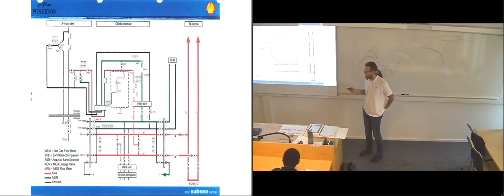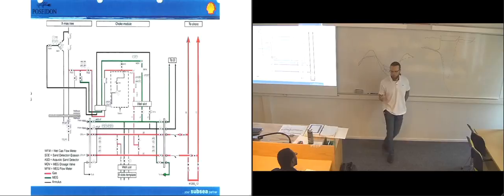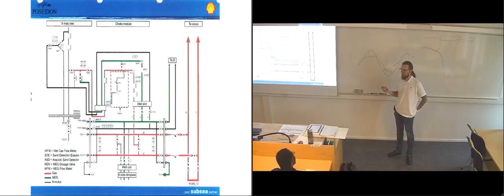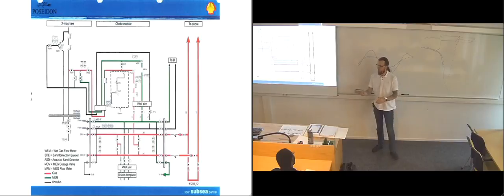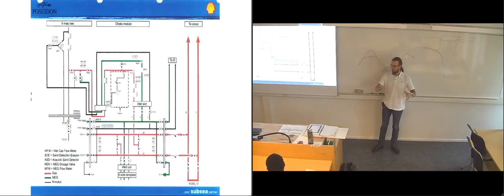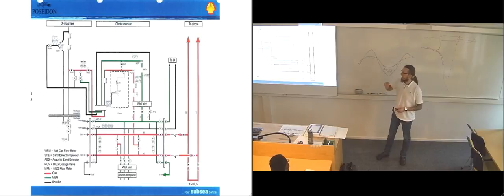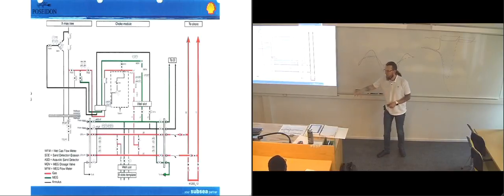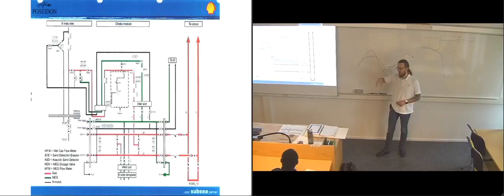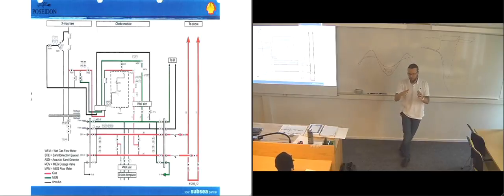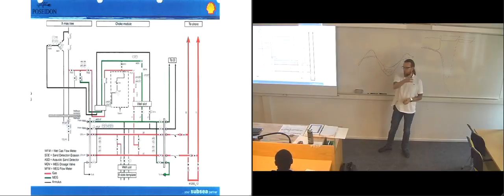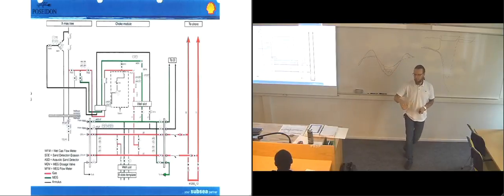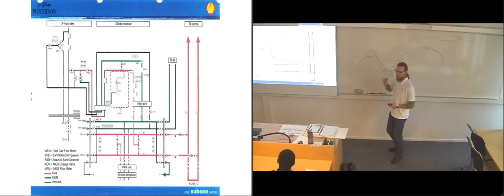I've seen some presentations where they could actually use these sort of very sensitive microphones, and they placed them just in the middle of a template, and it was just listening basically to the sounds that were coming from inside the pipelines. The sand was hitting the inside of the pipeline. This was vibrating the pipeline just very slightly. And the vibrations of the pipeline set the water into vibration, and these vibrations in the water reached the microphone. So basically they could hear straight away if there was sand in the system somewhere.